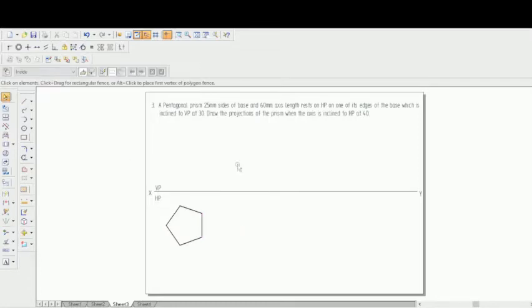Now let's name the corners of this pentagonal prism. See that the caps lock is switched off. This one, let's name it A. The top face as well as the bottom face, that is the base, both have to be named. The top face will be visible and the base is hidden, so let's name the base as A1. If the top face corner is named A, the base corner which is hidden is mentioned in the brackets as A1. Similarly this one B, and in the brackets B1. Similarly it will be C, C1, D, D1 and E, E1 in the other 3 corners.